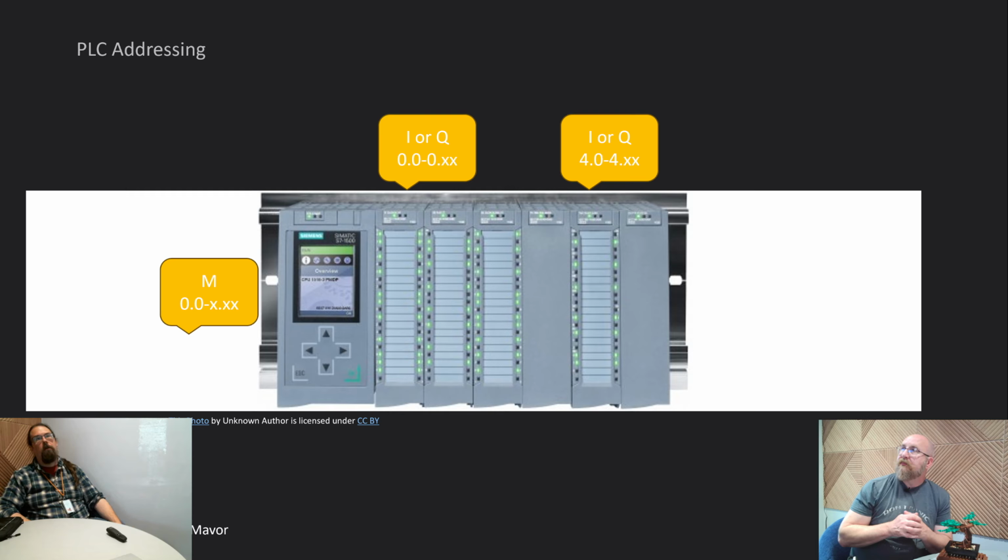Right, and thankfully, in the past, we would have had to do a lot of manual addressing of memory in this way. Yeah. Today, there are a lot of tools to help us manage this in a more effective and optimized way. And it all boils down to being thoughtful when you create your tag table. Yeah. When you're dealing with M addresses in particular, you have to be concerned with that. So think about blocking off areas for things that you know are going to exist in your program.